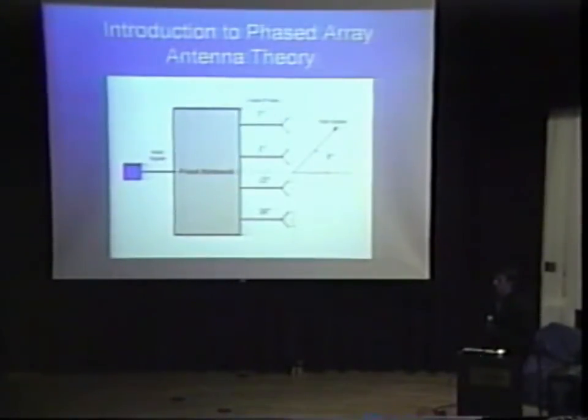To give you an idea of what exactly this means, the way phased array antennas work, the signal that you want to radiate goes through a feed network which splits it up into equal magnitude components going to each antenna element. Each antenna element is excited at a progressive phase shift. This one is beta degrees ahead in phase of the previous one, and they're all like that. This angle beta is related to the scan angle of the main beam. So by selecting beta, you can actually point the main radiation of the antenna with respect to broadside, or straight out from the antenna.